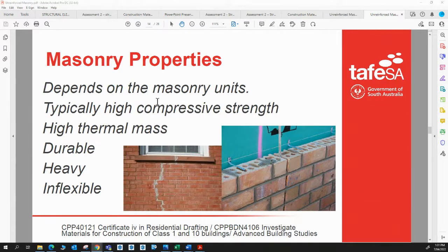But what typically gets done is the requirements for both of those joints get brought together, and we get the resultant rule that these brickwork control joints have to be spaced at 5 meter maximum centers in reactive soil situations, 6 meter centers for your medium to high reactive situations, and then at the edge of any window or any penetration in the wall which is greater than 900 millimeters, either high or wide.